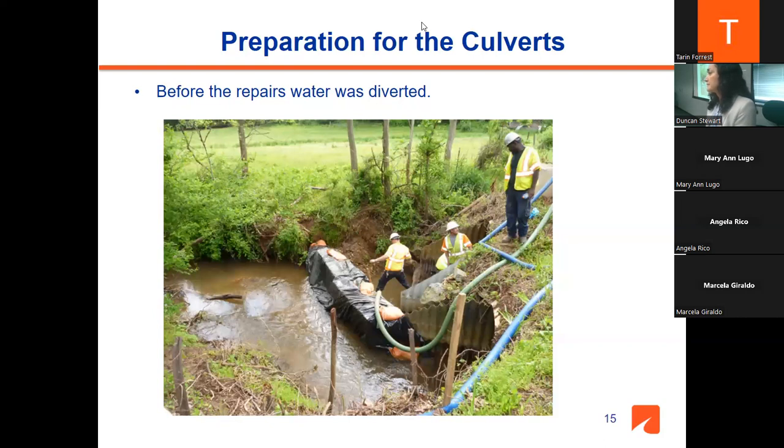I think the question is, these fibers we are using, are they from recycled materials? I really don't know, but what I know is this: the steel fibers we are using are domestic. The synthetic fibers came from Japan. They were the PVA, polyvinyl alcohol fibers, because they are very special fibers. They have an oil coating on those fibers, because you don't want the fiber to break. If the fiber breaks, the crack widens. So you want it to pull out of the system to release energy. So it is a very special fiber, the PVA fiber we are using. So it came from Japan.